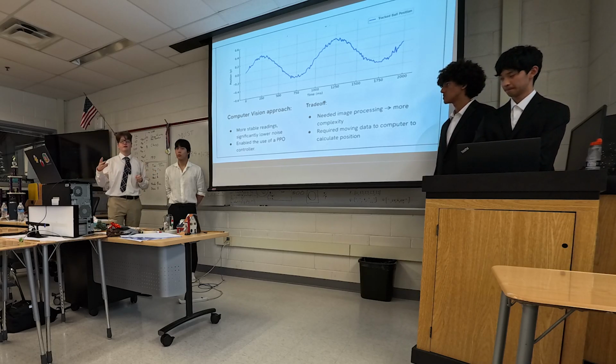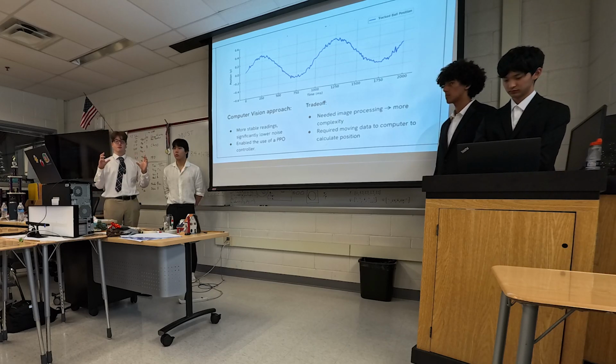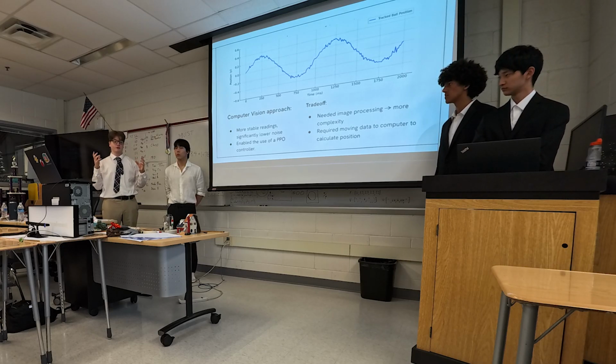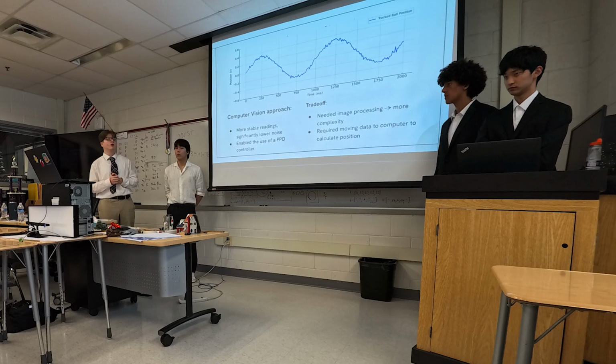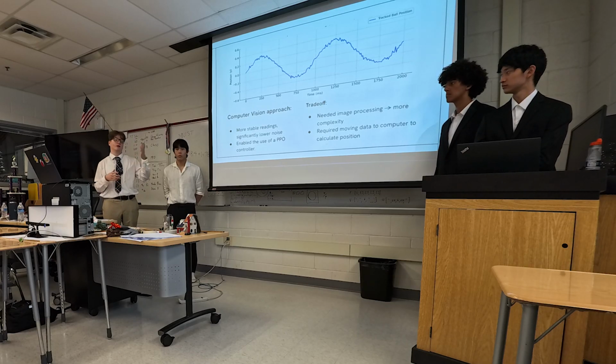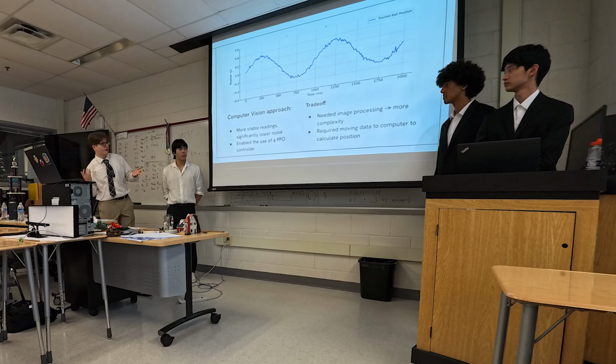But with the image, it's not quite as simple, as the image just tells you the position of the objects in terms of the camera, and I need to do calculations for those positions to be able to actually find the position of the ball in respect to the beam. And so that had to be moved over to the computer, which introduced a delay in between when the image was processed and when the action could be taken, which wasn't that much of an issue as I was expecting it to be. So it ended up working out fine.